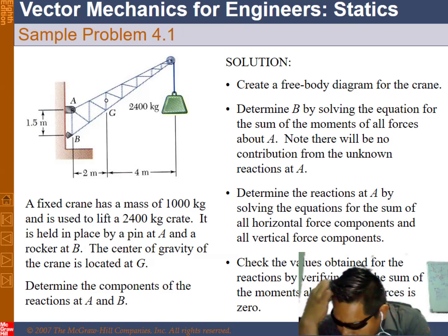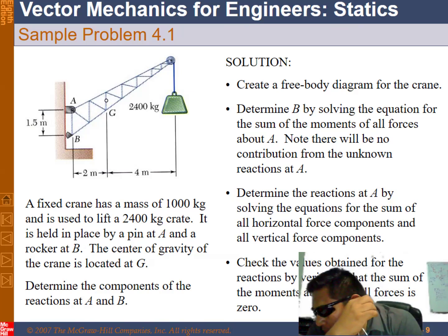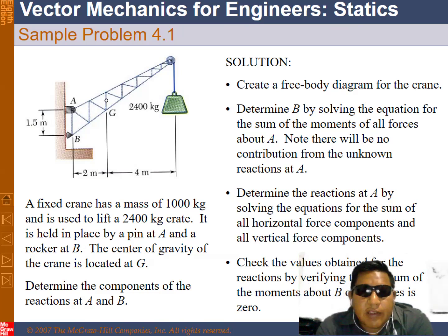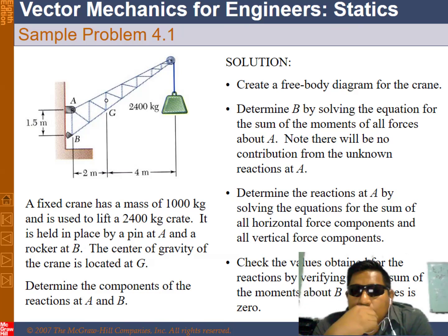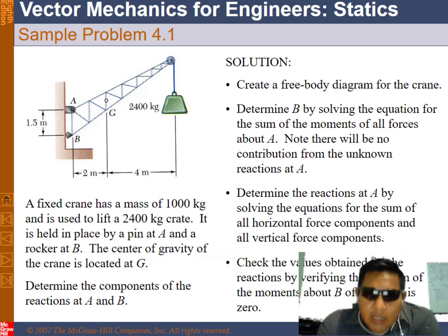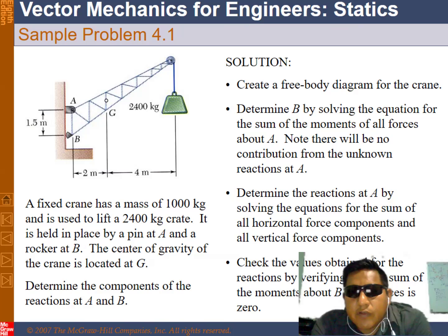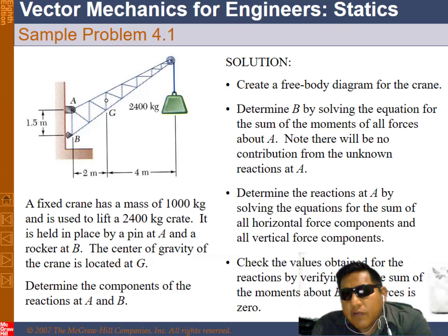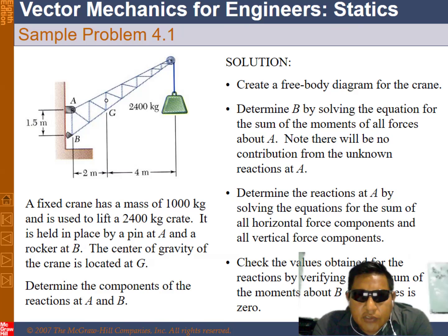What is the solution? Remember, the free-body diagram is the most important and is the first step. Create a free-body diagram for the crane. Determine B by solving the equation for the sum of the moments of all forces about A. Now there will be no contribution from the unknown reaction at A. Determine the reaction at A by solving the equations for the sum of all horizontal force components and vertical force components.